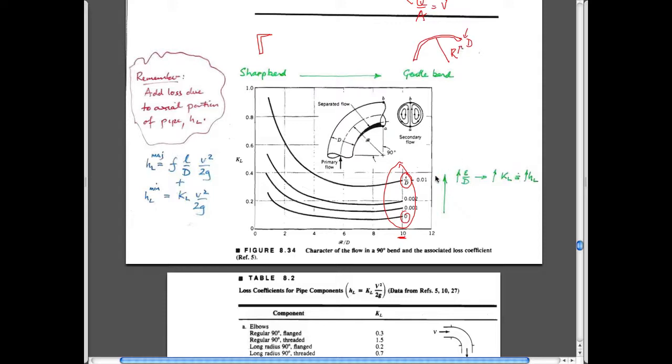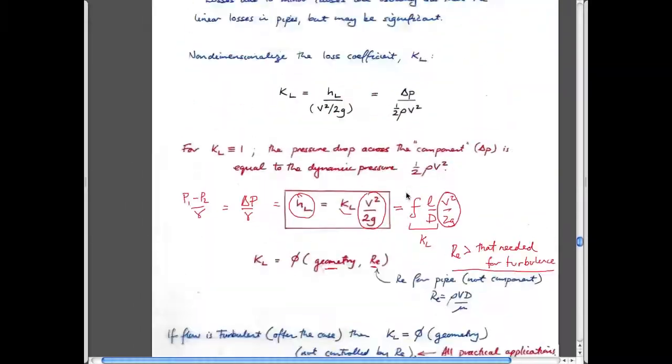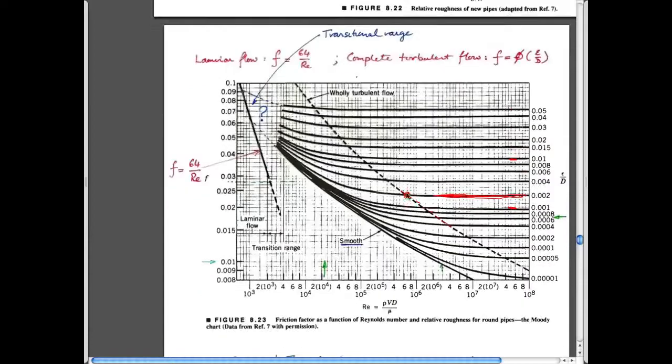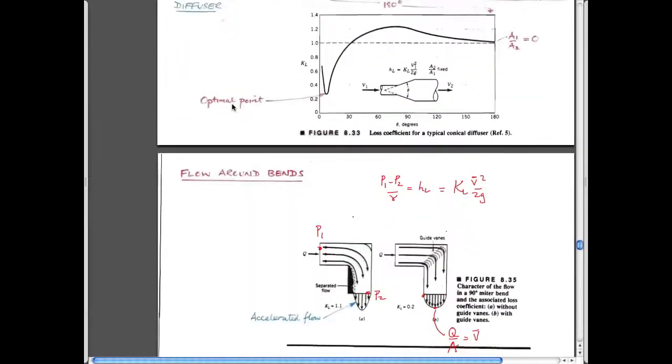I think. If the roughness is larger, you get more turbulence, you eat up more energy, and just in the same way as on the Moody charts, you end up being quite high up, this is a very rough pipe, this is a very smooth pipe, this is an infinitely smooth pipe with zero roughness, this boundary here. Then the magnitudes of the friction factor, which are proportional to the loss, are very small because you're down here versus being up here. And so it's just a natural follow-on from that. So hopefully it's very logical. I think it's quite logical.